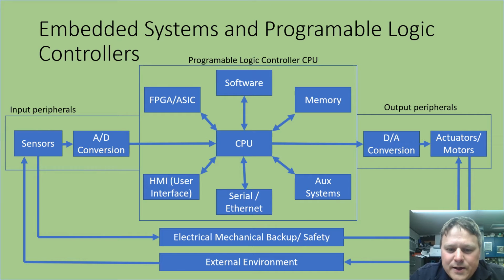So when we're talking about programmable logic controllers, or PLCs, we're talking about a modular system. Typically the processor is a standalone unit that mounts into a rack, and that rack connects to a lot of different peripherals that the processor can use to communicate or control the outside world. When I'm talking about the different peripherals, I'm talking about digital I/O, and analog signals coming in or out, so digital to analog conversion or analog to digital conversion. I'm talking about different communications topologies, either network based, serial, or servo control, but basically everything for the processor to communicate to the outside world and control that world.